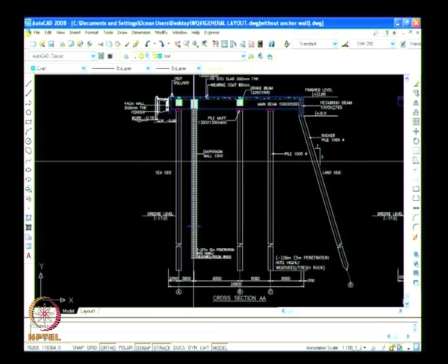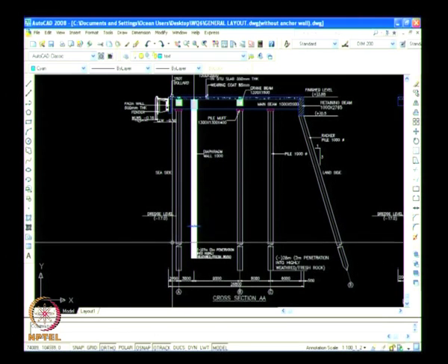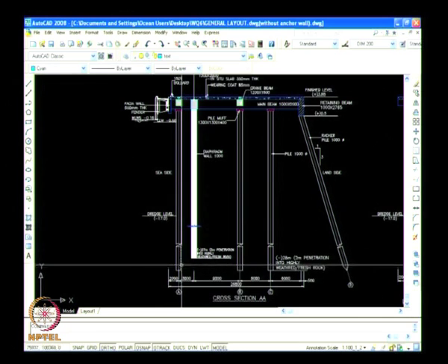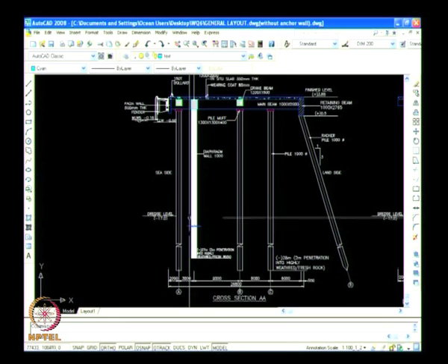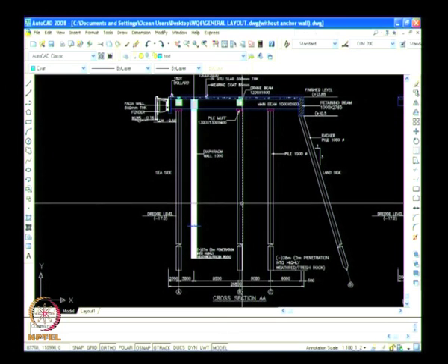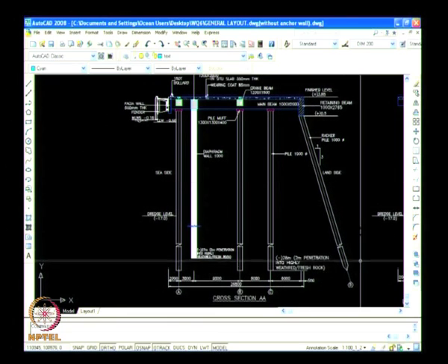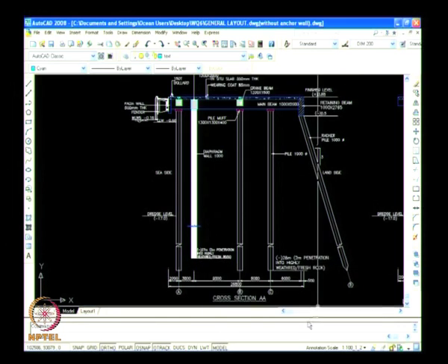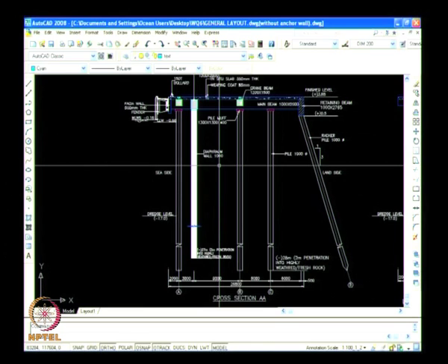So now we will see how to do a Staad Pro analysis for this, for which we want to model springs below the dredge level for the pile, here also below the dredge level for the piles for the diaphragm wall. Then we assume a 45-degree line, and then we put the spring below this for this pile as well as for the other pile also.